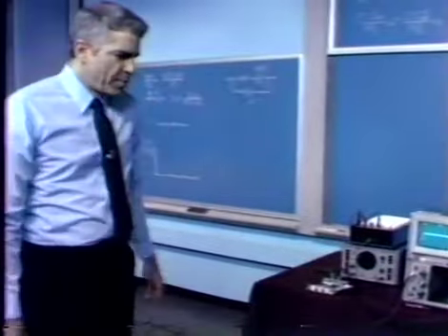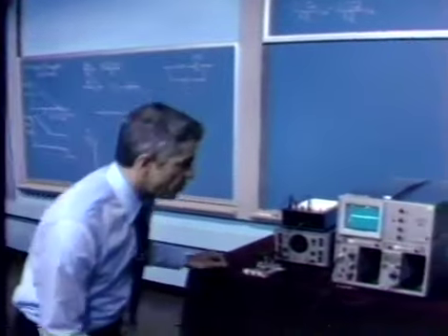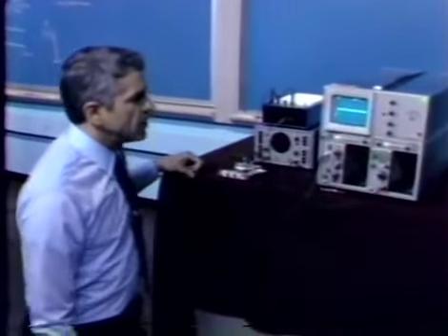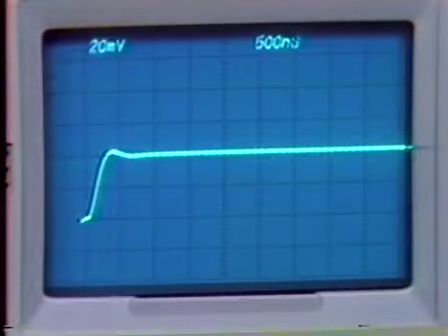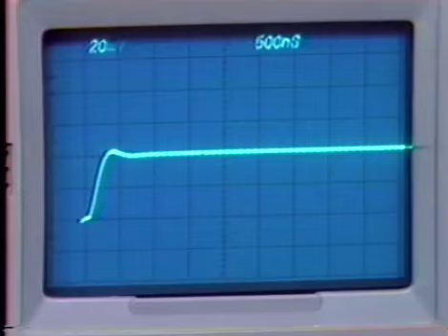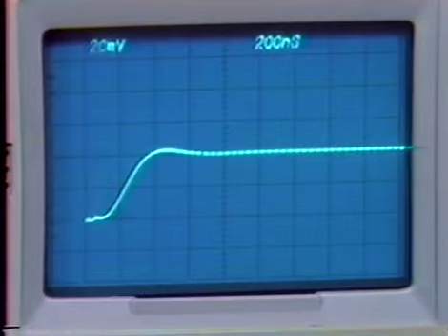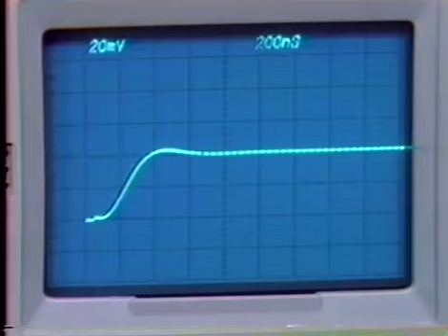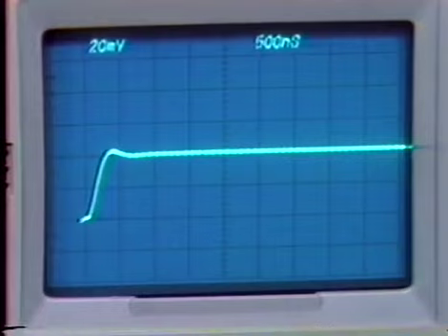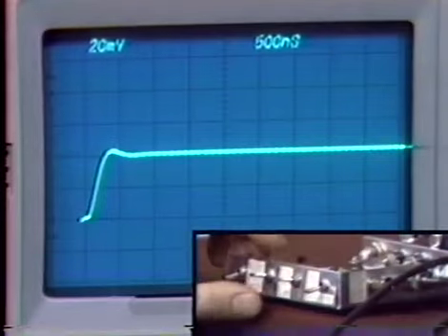At present we have the amplifier compensated for single pole operation, and we see the resultant step response on the oscilloscope. We're using about a 20 picofarad capacitor with this particular amplifier, which is the same one we used in the last series of demonstrations. We get a 10 to 90% rise time of about 200 nanoseconds with that value for single pole compensation, implying that the crossover frequency for this configuration is somewhere in the order of 2 megahertz. And this is operating without any capacitive load.